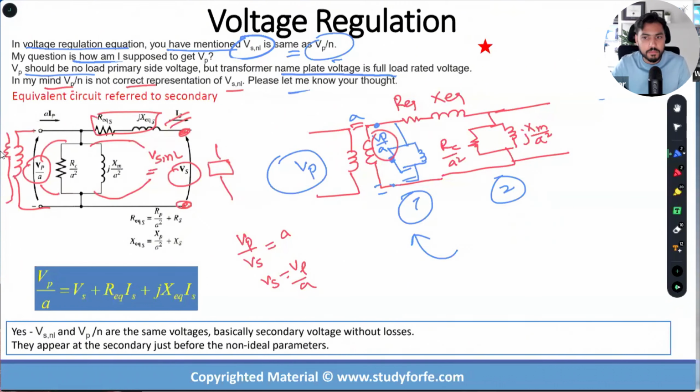All right, guys. As far as the equivalent and the approximate circuit is concerned, and this is something that shows up in induction machines as well, if we bring the parallel parameters, the core parameters, close to the source of the voltage, it's considered approximate. The easy thing is that we can then apply the voltage directly across the series arrangement as well as the parallel arrangement.